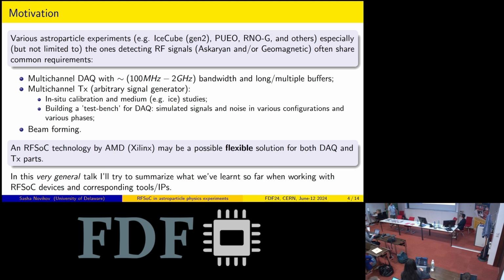Also, for PUEO, right now we're working on building a custom test bench for the DAQ. The idea is that you have a multichannel signal generator, and you insert simulated signals, let's say from neutrinos, and noise, like anthropogenic noise and thermal noise. You want to synchronize them very well and set custom delays to test your DAQ thoroughly, because this is essential.